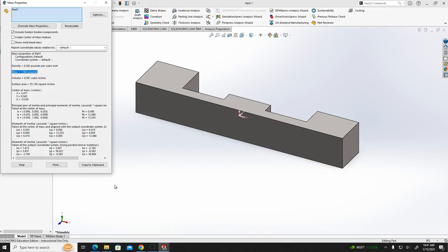I would just click from here. Hold on, you're not in the edit sketch. Use Smart Dimension on that corner. Now drag it, then double click on it and you can see the number there.